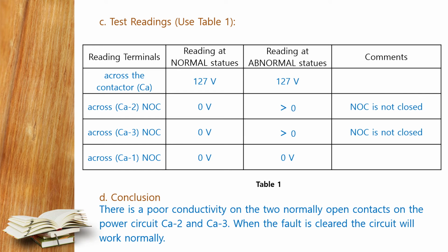It was said that when we press the low speed, the motor runs in low speed normally. When we press the medium speed, the motor doesn't go to the medium speed. But when we press the high speed, the motor moves from low speed to high speed immediately without passing through the medium. This means that in the control circuit we are fine because this is the sequence. We can operate the low speed, then medium, then high, and this is what we have done.